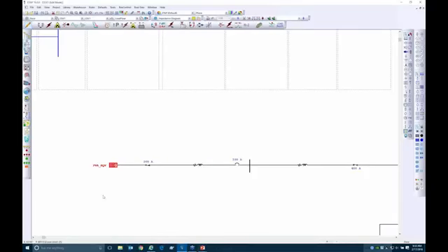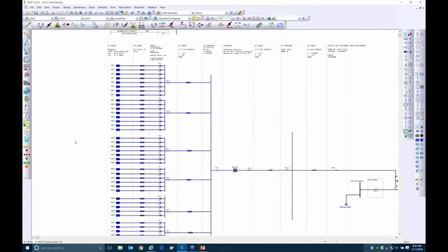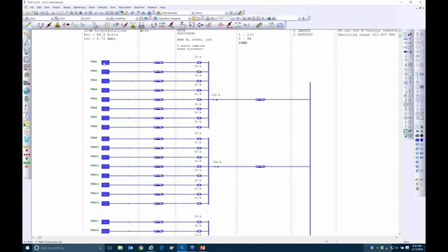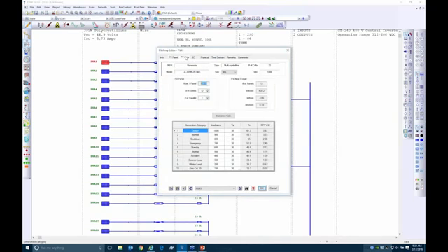So if we look at the same PV array, which is an equivalent, I have 564 panels here with an inverter injecting power into the network. If I step back to my diagram here, this is exactly the same system. If I open up one of these panels, you will see it's the same panel here, 12 of them, but only one in parallel because I'm representing PVA1 as one string. And that's my choice in this particular system.